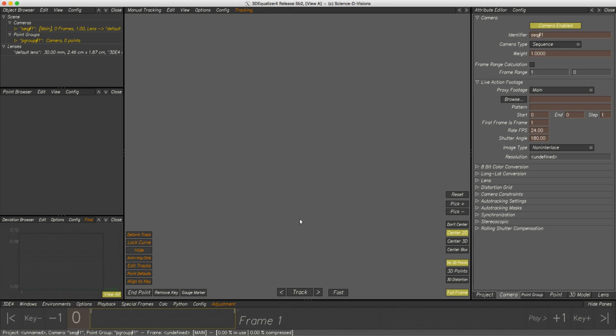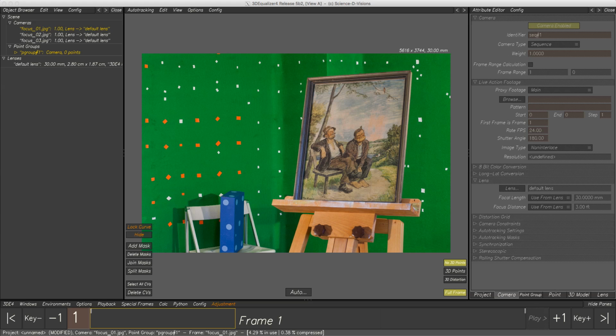The very first and important advice when shooting reference frames is, it is highly recommended to shoot all reference frames with the same focal length setting. That way, only a single lens object will be needed here in 3DE4, which enhances the project's simplicity tremendously. We all know, having a set of images with different focal lengths is a huge pain in the you-know-where. So, to prevent the tedious work of creating and adjusting multiple lenses in 3DE4, do not touch the lens object of the camera once it was set.